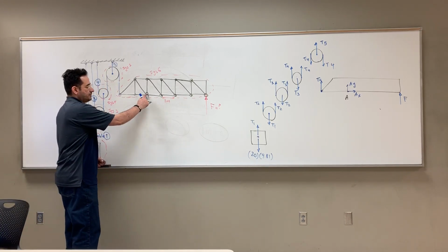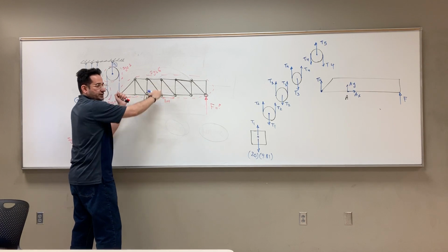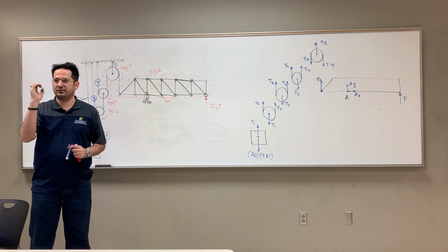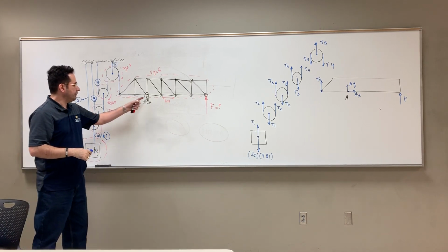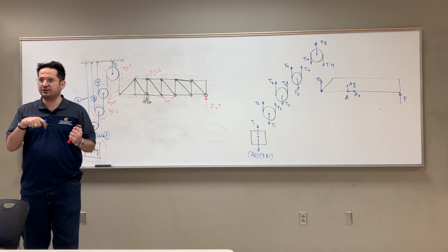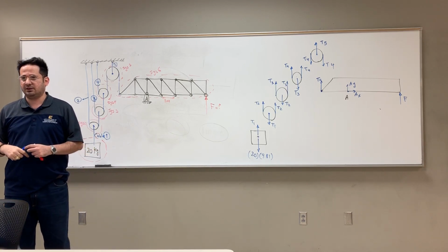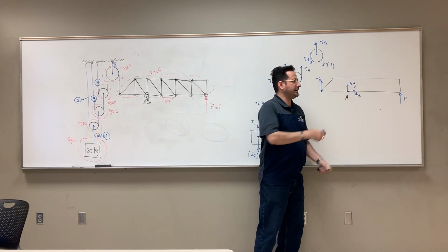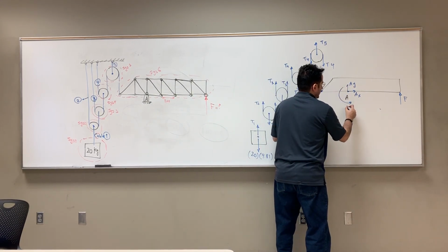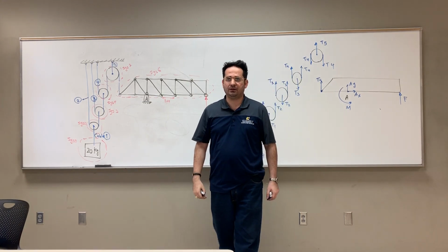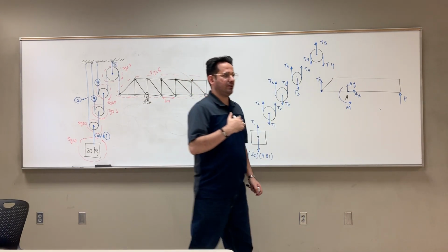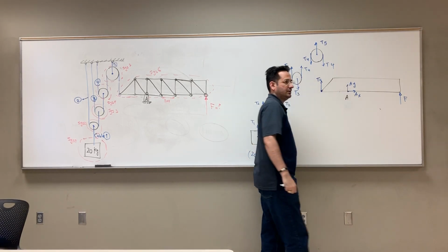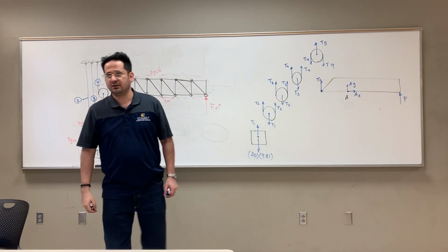Well, this is a pin, right? This can easily rotate around point A. So no, there is no resisting moment. Let's assume that this was welded here. If this was welded here, you would have an unknown moment too. So in addition to AX, AY, two components, you would have unknown M if that was welded to that point. But right now, it's just a frictionless pin, so you can easily rotate it. So nothing is resisting you. There is nothing, zero.